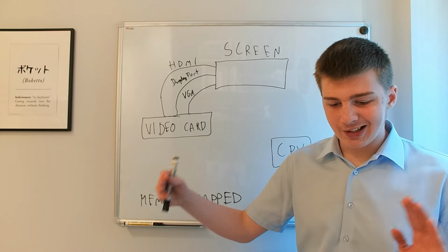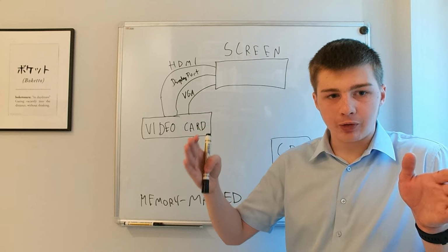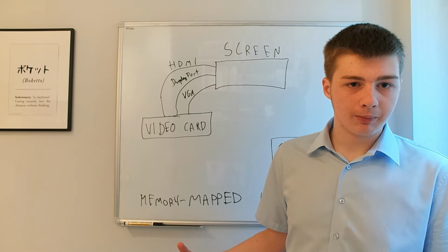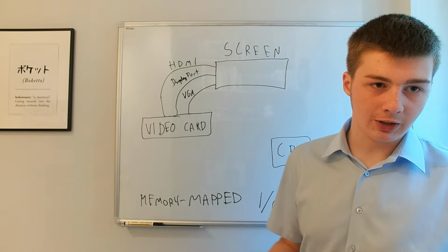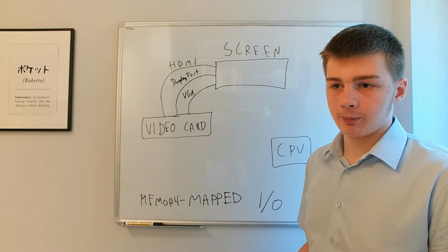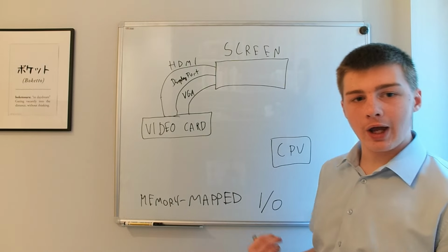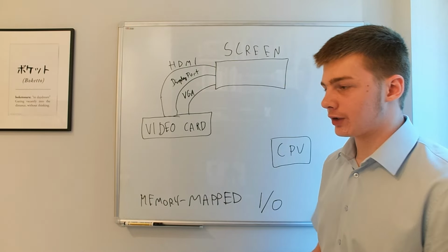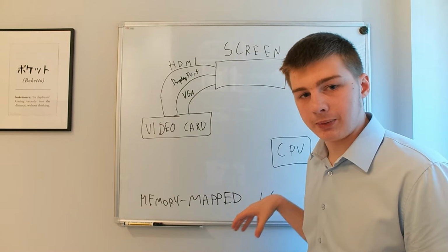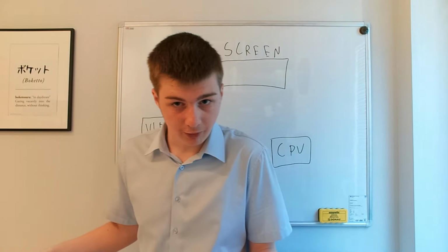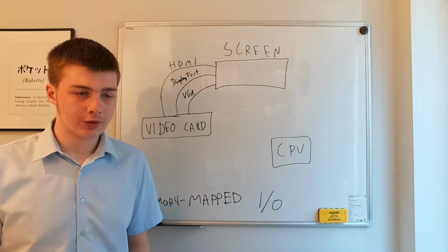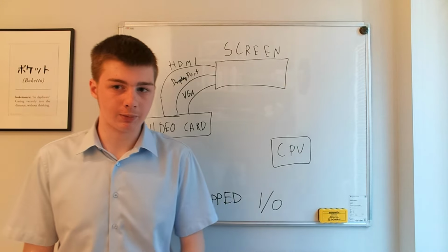The peripheral device or the extension card continuously, every cycle or every couple of cycles, checks this buffer in memory and treats it as information in a given format. So this is the general idea: have given regions of memory called buffers that are responsible for storing this information that can be used.